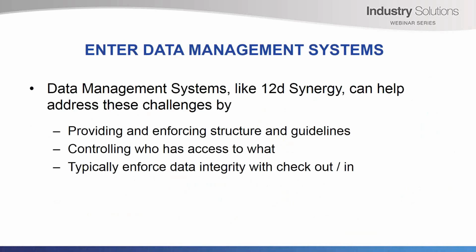So for those of you who haven't used data management or 12D Synergy before, what you tend to do is access a file by checking it out first. While you have it checked out, nobody can access it, or rather no one can write to it, but people could read the old version. When you're done, you can check it back in and release it to everybody else. That also gives you the ability to keep an audit trail of your data. So you always know who changed it, when it was changed, and why it was changed.